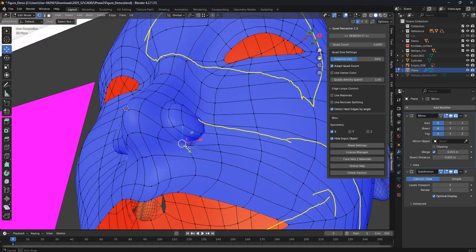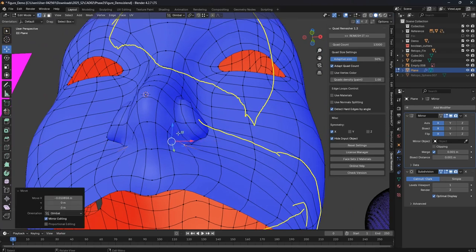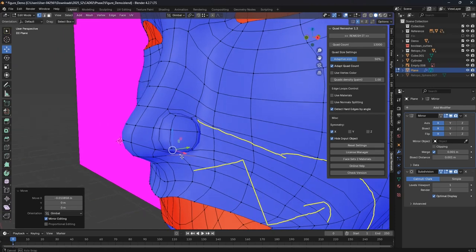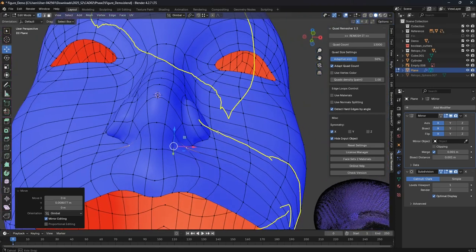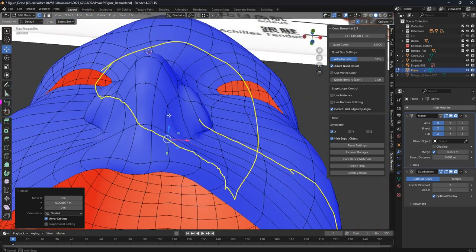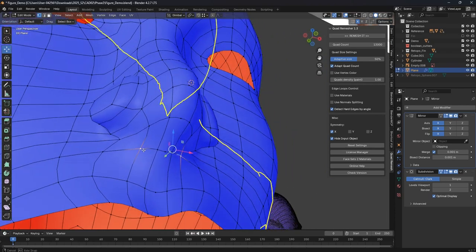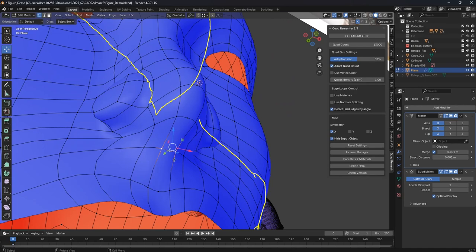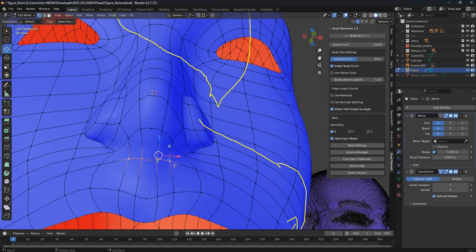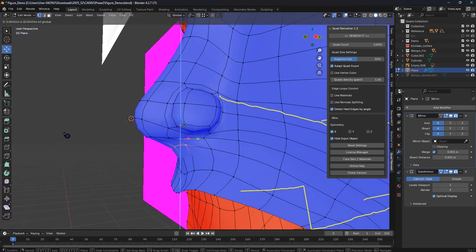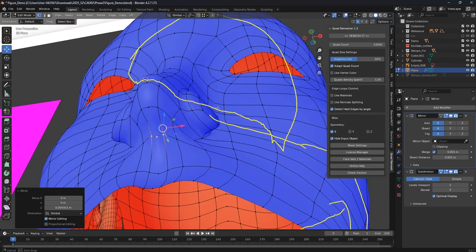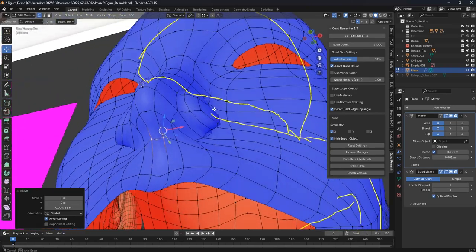Okay. And how about the nose holes on your model? For the nose hole, it's very simple. You just simply choose a face and extrude it inside, it will be fine. For me, in this case, wait for a second, let me refine the shape on the bottom side. So now let's start to extrude the nose holes.